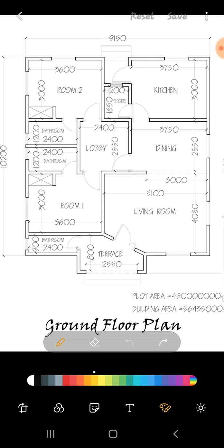Now the building height is a combination of the height of block work from foundation level up to the damp proof course, which we also call the DPC. From the foundation to the damp proof course is usually about 3 courses of block work, and that gives you 675 mm. And then from the damp proof course level up to the roof level is a standard height of 3 meters. And so in this case, we don't want to break them.